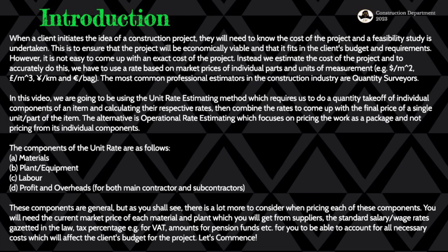You need to find the smallest quantity of that whole, and then you price that small quantity, and then you multiply it with the entire quantity or the entire item. So that square meter of a wall, you then multiply with the walls that are on that building, because they have the same material, they have the same composition of those materials. They're not just the same, but they're also in the same quantities all around. So you just multiply with the rate, and then you get the total price for that project.